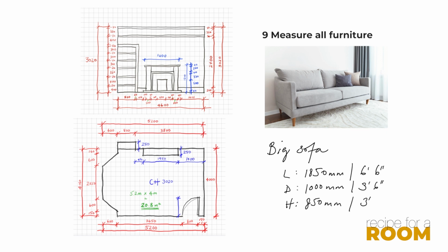And I also take measurements of all the furniture in the room so that I can make movable templates for each piece. That way I can try out different furniture layouts without physically heaving heavy furniture around the room. For a lighting plan, you do need to have all your furniture sketched into the preliminary drawing so that you can ensure that your general task and accent lighting ends up in exactly the right locations. And voila, the survey is complete.